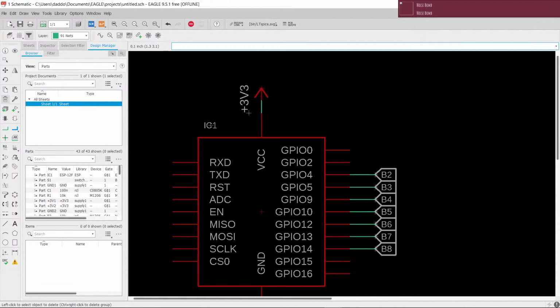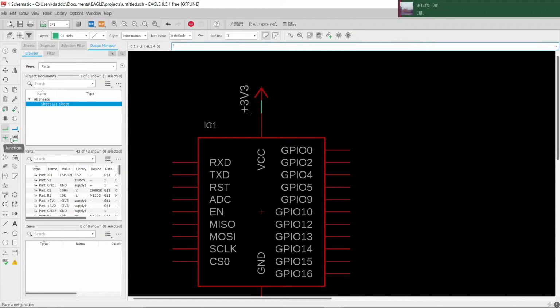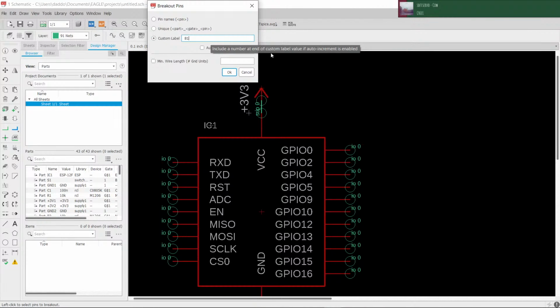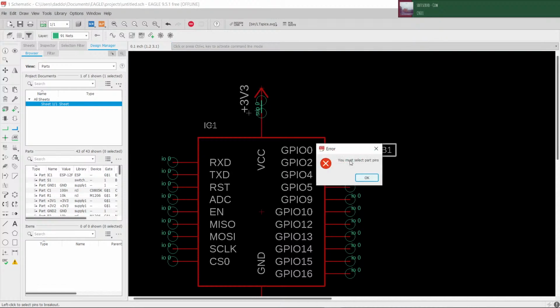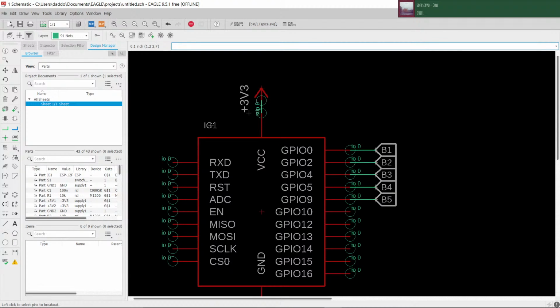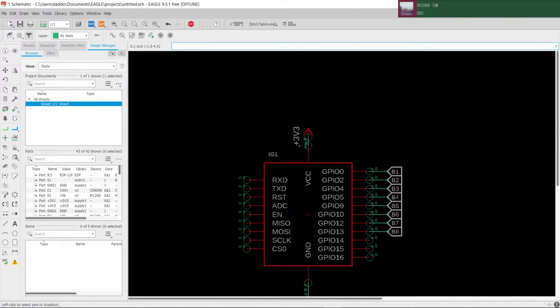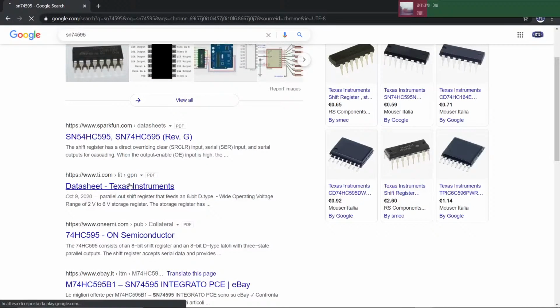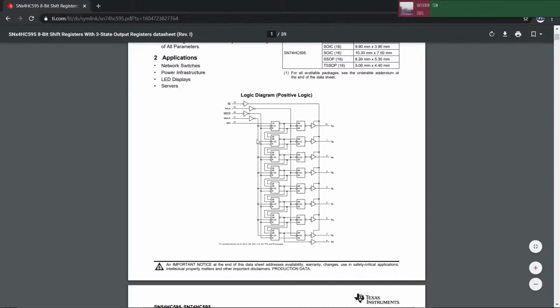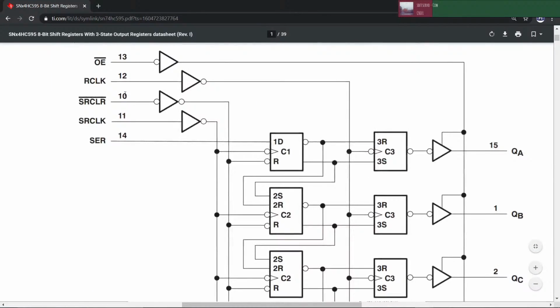Yeah, let me actually redo this connection. See here, and also the labels should be 05. Nice. Okay, net B1, auto increment 6 grid lines I want. B1, B2, B3, B4, B5, B7, B8. And let me add the shift register. I can use the SN74595, which is a pretty standard shift register that is used in plenty of things.